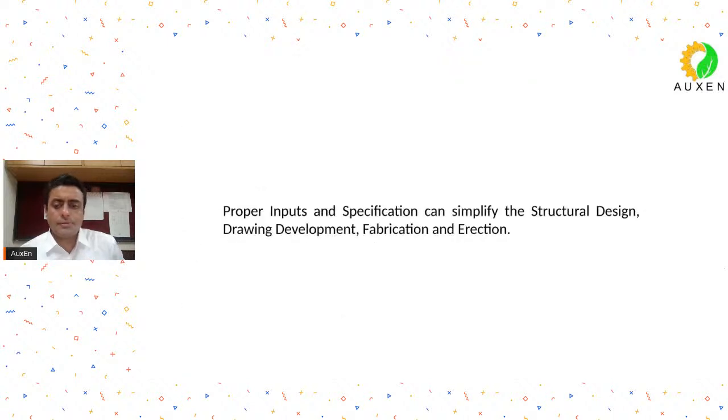Overall, these were the main inputs and main specifications you can ask from your client before starting the structural design. If you get all these inputs properly, it will help you not just in the process of design but also in drawing development, fabrication, and erection works.